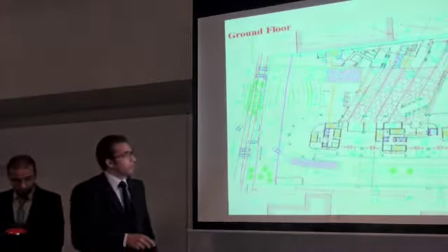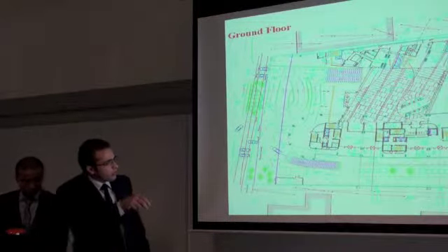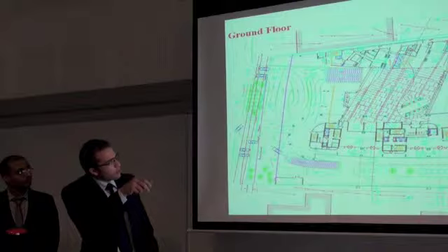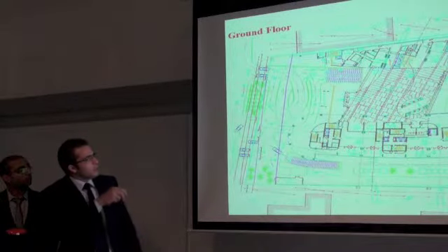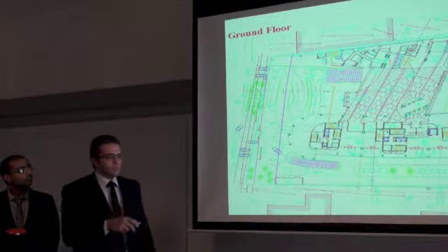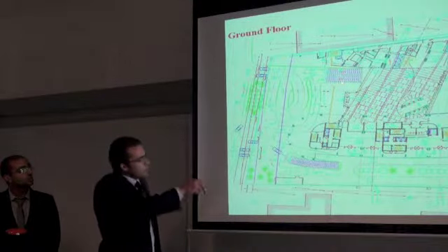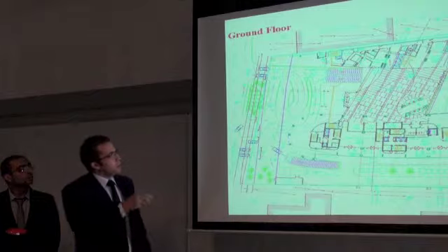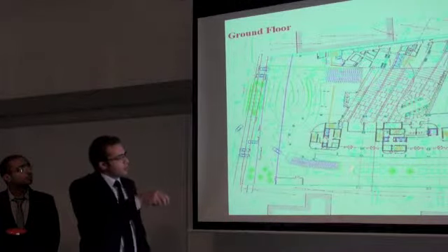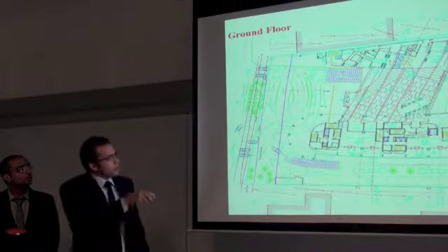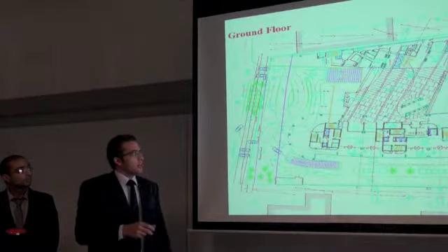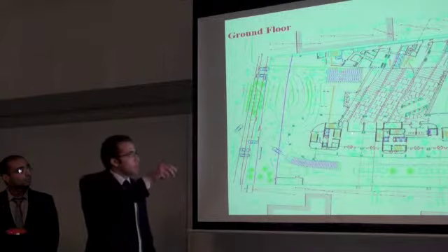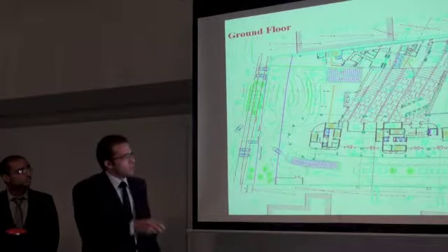This is a plan for the ground floor. Here is the outline of the first building and the layout of the second building. The street and the Nile are on this side. The entrance is here, and we have 3 ramps leading to the basements 1, 2, and 3. Here are the neighbors, here and here and here. We have a steel truss in the middle between the 2 buildings at a height of 4 floors, and we have a steel shed at a height of 3 floors.